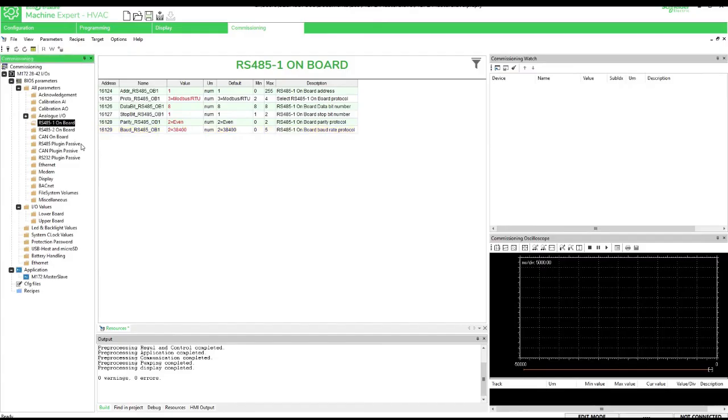The same applies to the RS485 port in passive serial mode. Parameters defined in commissioning are not active at runtime. A device reboot is required. Alternatively, slave settings can be adjusted by defining custom default values in the parameters.